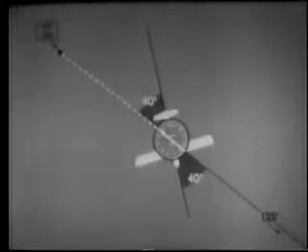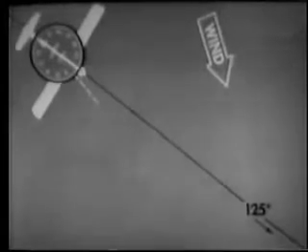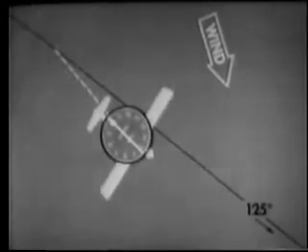We will be on track when the ADF needle is 40 degrees right of the tail, or a reading of 140 degrees. With our heading now 125 degrees, the ADF needle at 180 degrees, we are on the 125-degree outbound track. For outbound tracking, we use the same basic procedures as we do when tracking inbound. Only as we drift off track going outbound, the needle will be deflected from the 180-degree or tail position, here 185 degrees.